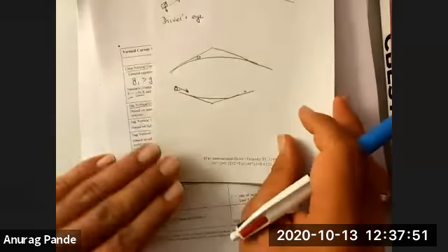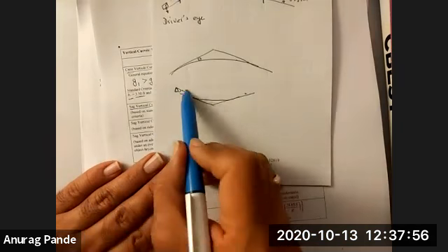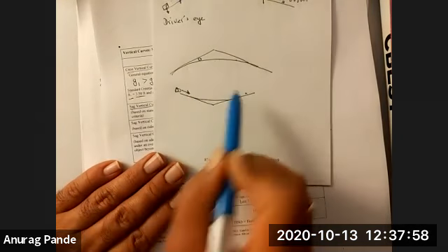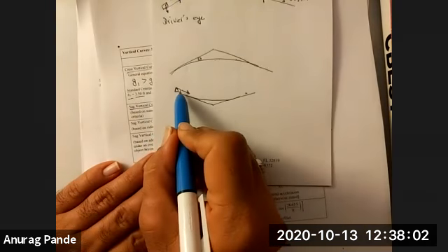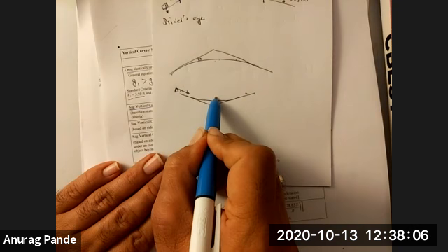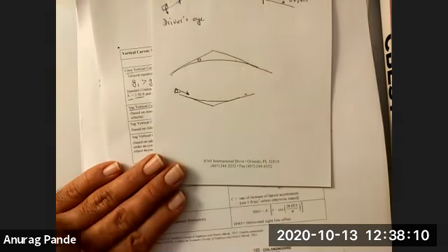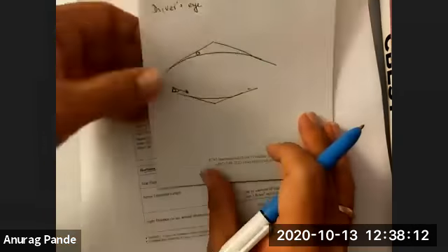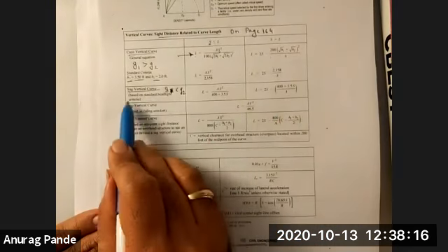We need these formulas not for daytime driving conditions, because in daytime driving this is never a problem. But in a nighttime driving condition, your headlight might only illuminate a certain distance of the curve. These formulas are in fact derived based on standard headlight criteria.